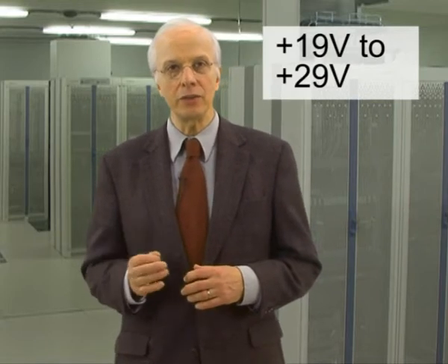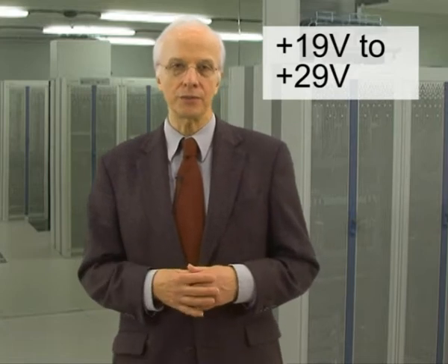A DC load is any kind of equipment that draws power from a DC power supply system. In our case, the load consists of telecom equipment. Power and climatic systems provide the load with energy and the right operating climatic conditions. The normal operating voltage window of Ericsson telecom switching equipment is minus 40.5 volts to minus 55 volts. Normal operating voltage window for plus 24 volts RBS systems is plus 19 volts to plus 29 volts.